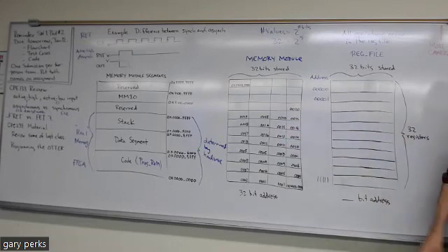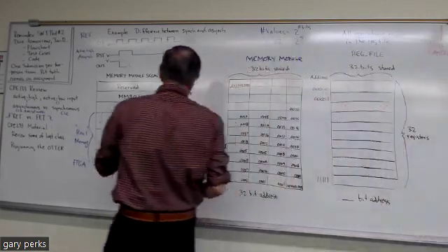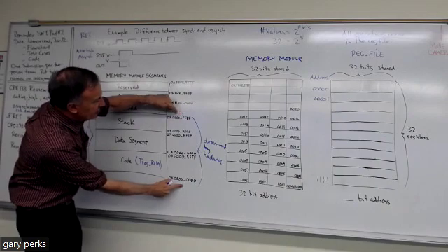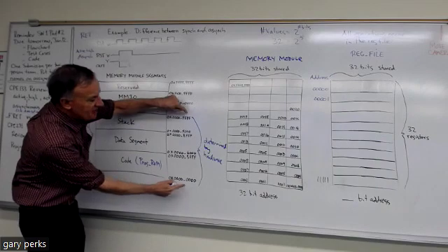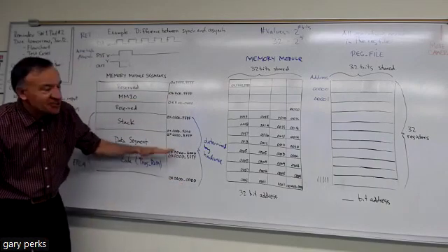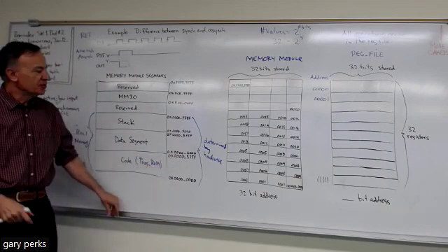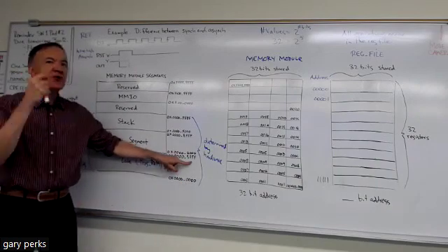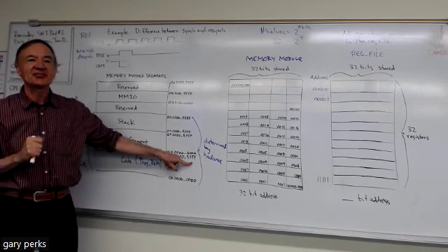One other point I wanted to make is that this range of addresses from 0 to 0000 FFFF is set by the FPGA. That's hardware limited. But how the segments are divided up, the programmer decides. The fact that the code goes from this address to that address, the programmer decided that. In fact, it was Dr. Hummel, one of the designers.